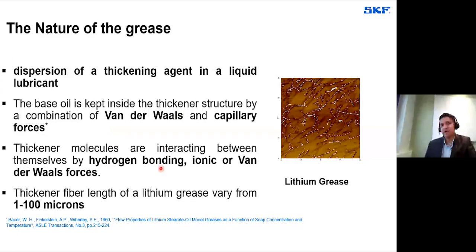In the same way, thickener molecules can also interact between themselves, mainly by hydrogen bonding, ionic bonding, or even by van der Waals forces. If you take an example of a lithium grease, then the thickener fiber length may vary from 1 to 100 microns. What you see here is a 2-dimensional image of a lithium grease. It's a simple lithium grease with mineral oil. This image is taken by using an instrument called atomic force microscopy, AFM.